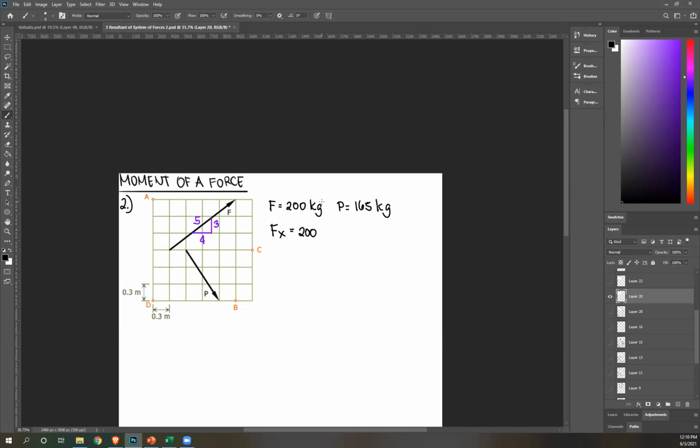I'm not multiplying this by gravity to get weight because it was not specified in our problem that we need the unit Newton. That's why I'm still using the unit kilograms. So, sustaining that 200, to get the x component we need the horizontal side. So that's 4 times 4 over hypotenuse 5. Please compute what's the answer. 160, correct.